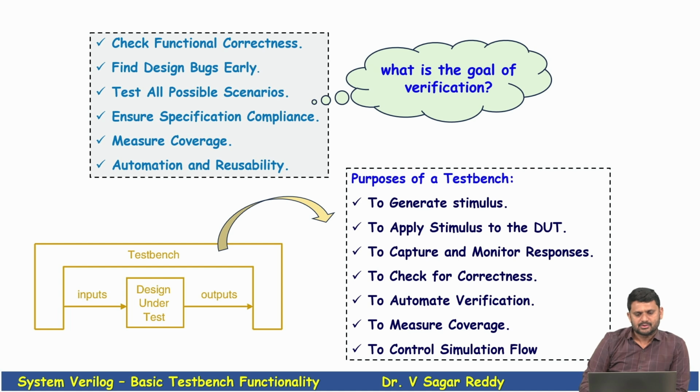To conclude, a test bench is a verification environment built around the DUT that drives the stimulus, monitors outputs, and checks the results against expected values using scoreboards and checkers, and measures functional coverage also. Everything is done automatically, so it removes manual effort, catches functional bugs early, and gives us complete confidence in the design before synthesis. The key takeaway is that no matter how perfect your RTL design looks, it is the test bench that proves it actually works. Without a robust test bench, verification is incomplete and your design is always at risk.